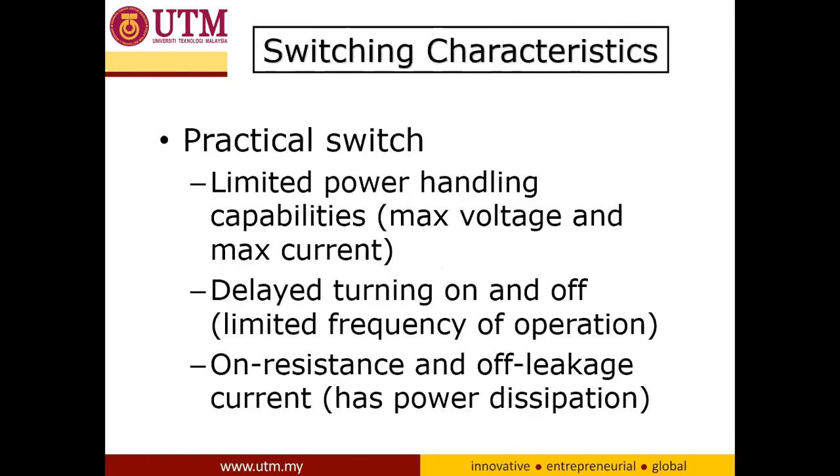But in practice, they are different because they are produced from semiconductor, from a silicon material. So there are some characteristics that you need to consider. The practical switch has limited power handling, so when you are designing a circuit, you need to know the rating of your power devices.